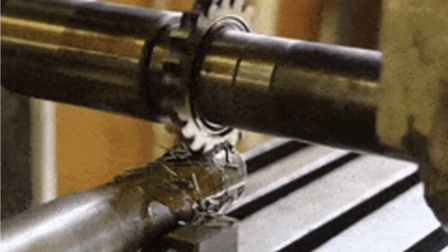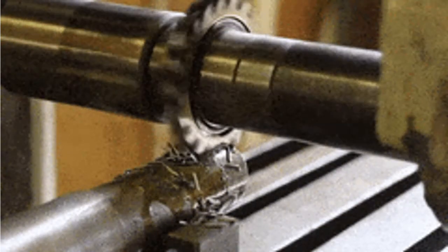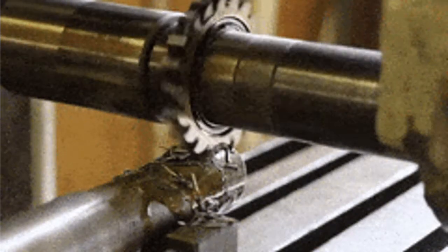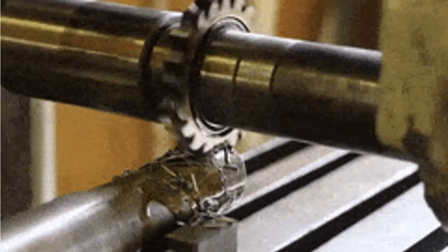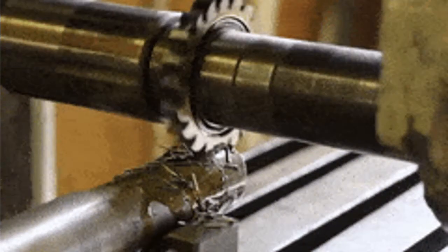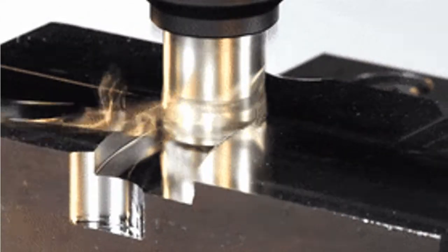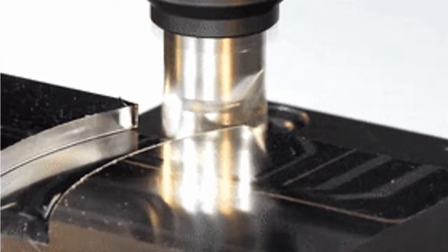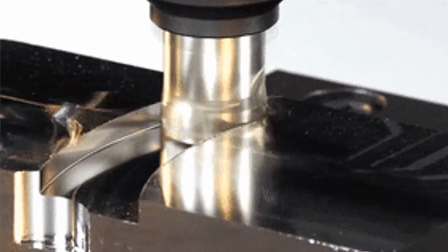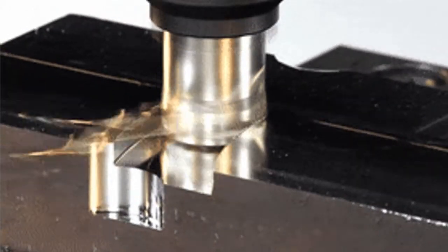A horizontal milling machine has a horizontal spindle, and this design is well suited for performing peripheral milling, like slab milling, slotting, side and straddle milling, on work parts that are roughly cube shaped. The vertical milling machine has a vertical spindle, and this orientation is appropriate for face milling, end milling, surface contouring, and die sinking on relatively flat work parts.